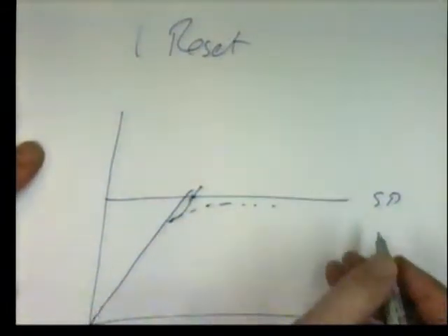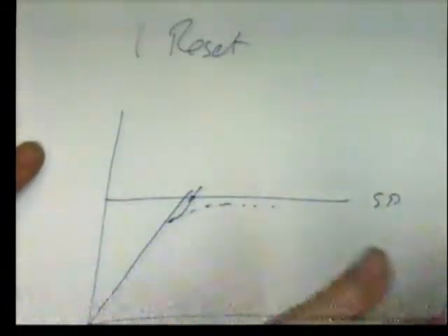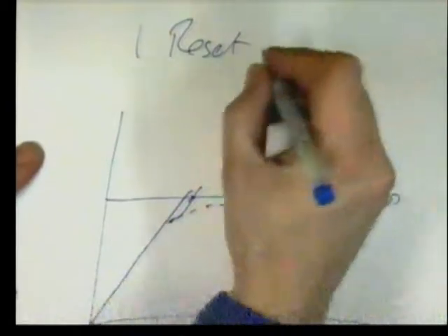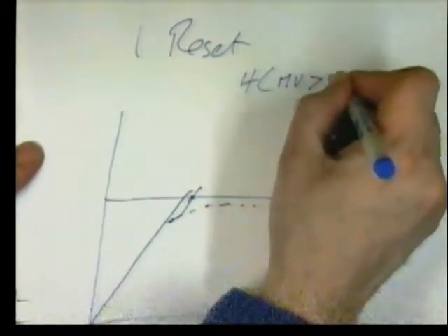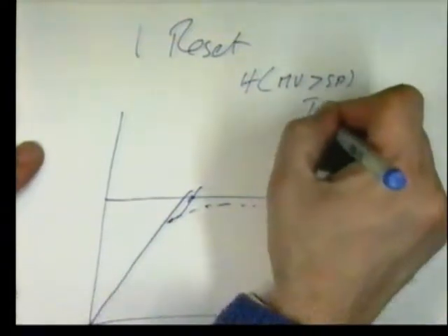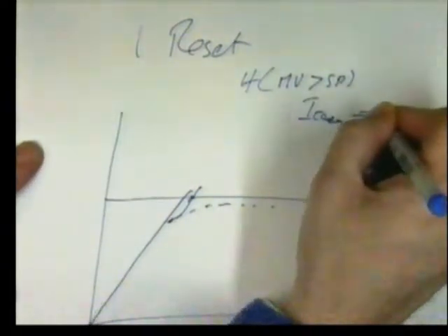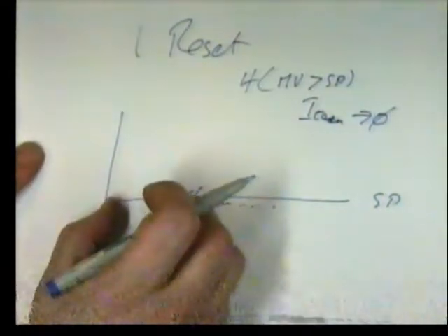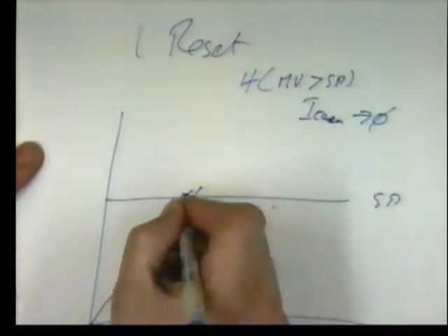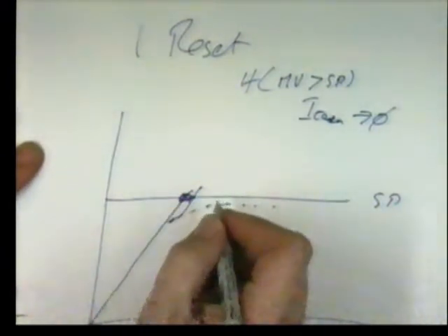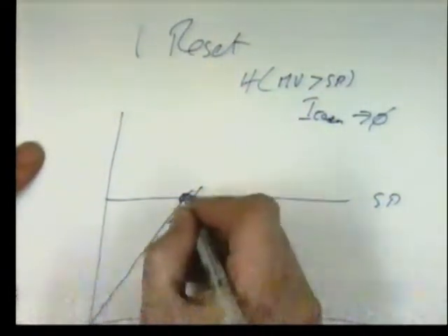Once we've crossed the set point, it's done its job. Get rid of it. Switch it off. So we say that if the measured variable is greater than the set point, we set the whole of the I term to 0, i.e. you just clear the array. Bear in mind you've got this array that is following the last 128 samples. As soon as you detect you've crossed the set point, you do a memset 0, clear the whole of the array out, and the I term disappears.